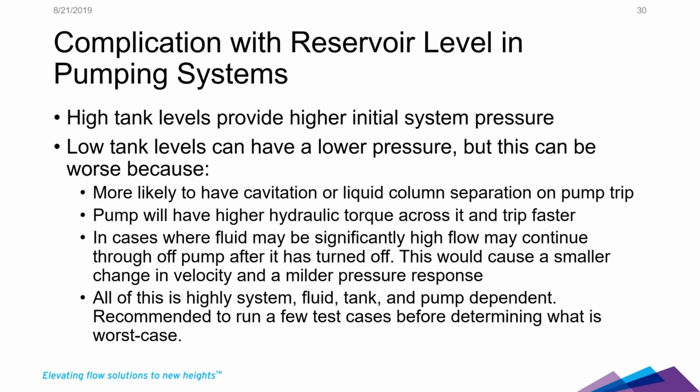Okay, reservoir levels in pumping systems is also kind of important. You can think of this like, okay, I have a tank and it can be empty or full or somewhere in between. Somewhere in between might be kind of boring. Maybe nothing happens there. But you can think of high tank levels could potentially provide higher initial system pressures. Yeah, that's true. Maybe you'll be more likely to overpressurize your system on a valve closure if your initial pressure is higher. That makes sense.